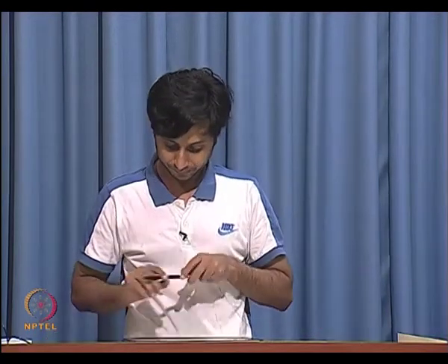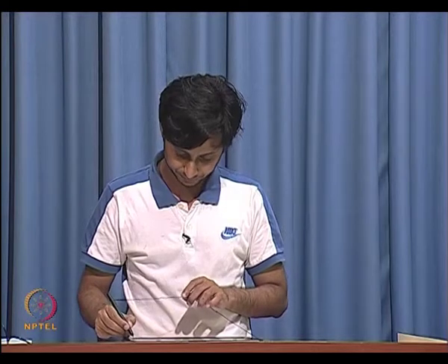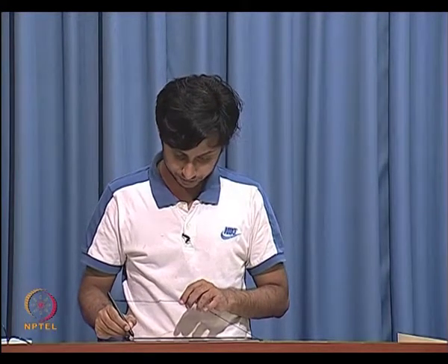Welcome to lecture 6, CMOS RF integrated circuits. We were discussing matching networks. In particular, we had discussed the L match in quite some detail, and then we decided that the L match might not be the end of the story, because there are only 2 degrees of freedom. So, this is what we had done in the previous lecture.